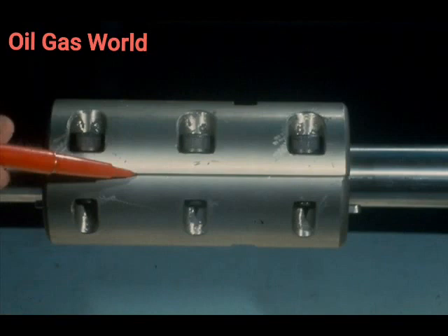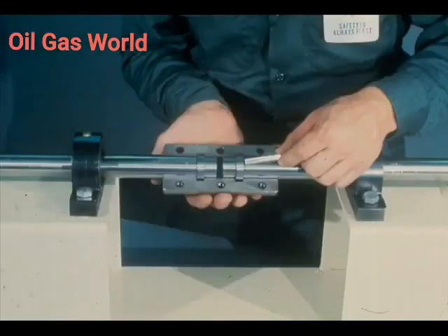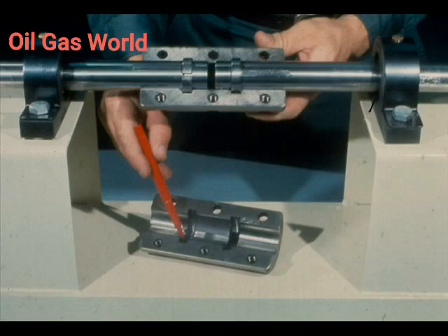As you can see, it is made up of 2 halves which are bolted around the shafts to be connected. Let's remove one of the coupling halves from the shafts now and show you how the coupling works. As you can see, there is a keyway in the coupling half and in the shaft. This key then prevents the 2 shafts from turning within the coupling. There are also 2 other positioning grooves that resemble keyways around the inside circumference of the coupling.